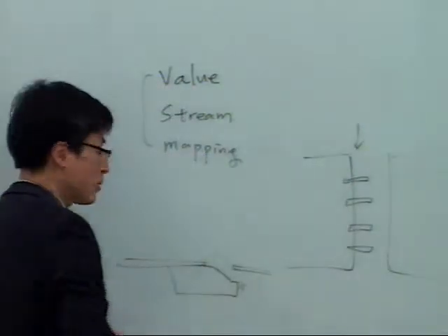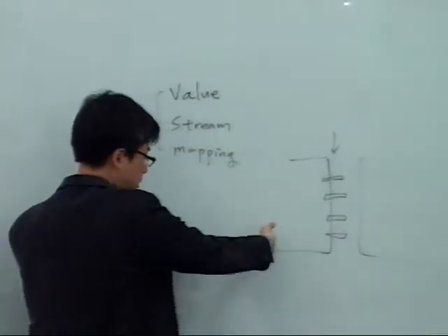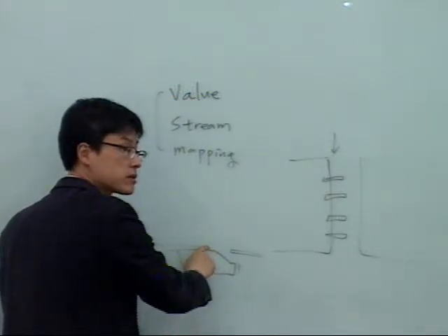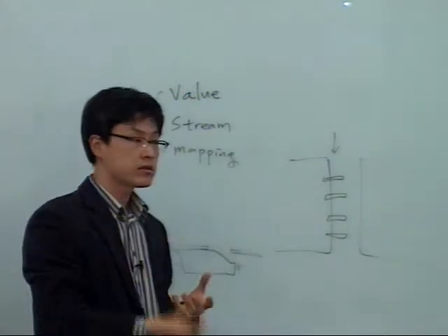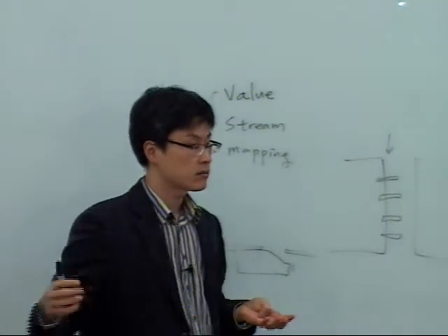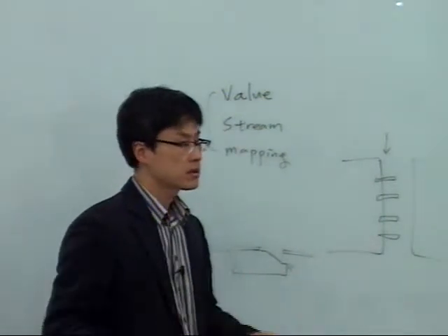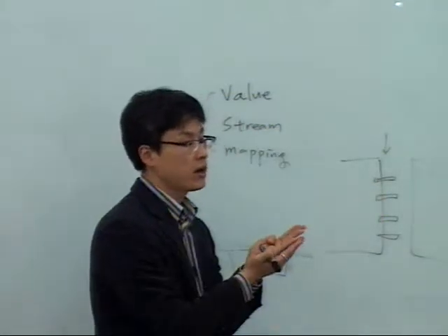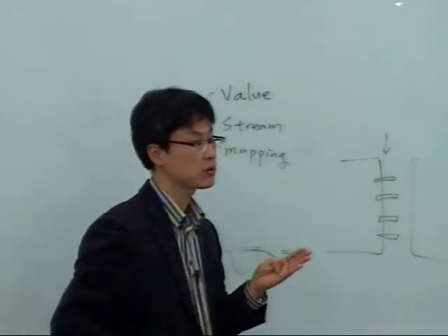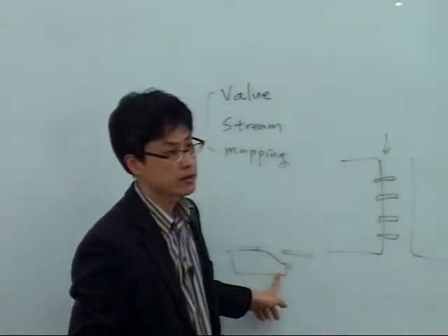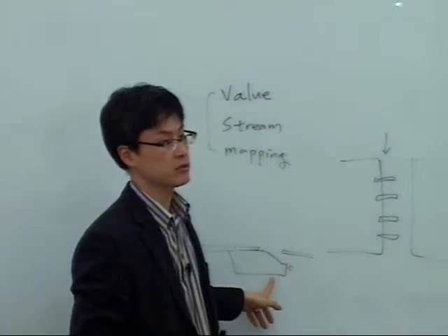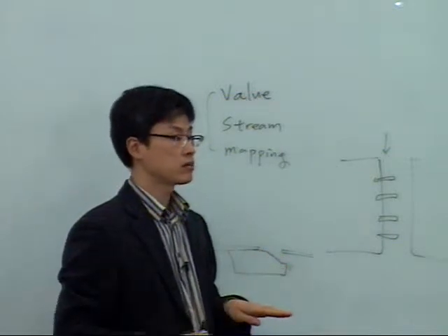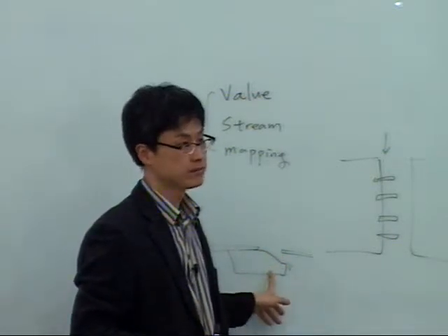The outer plate of the other block can be easily fit, and if you just pull it together, it will automatically fit to the right place. Manufacturing these guides, moving them around the shipyard, attaching the guide here, and after aligning and welding it, you have to remove the guides. It's a non-value-added thing. You've got to eliminate this one. So the right answer is to assemble the block together without this guide.